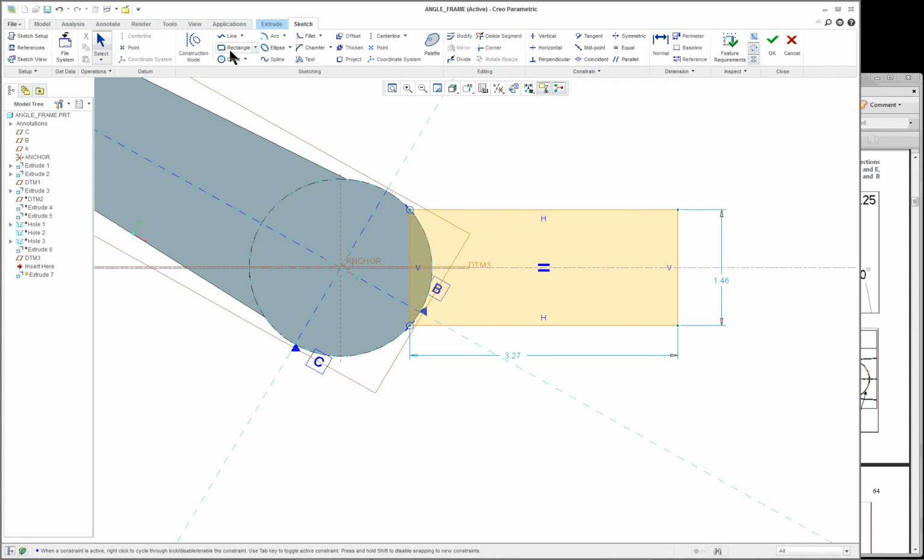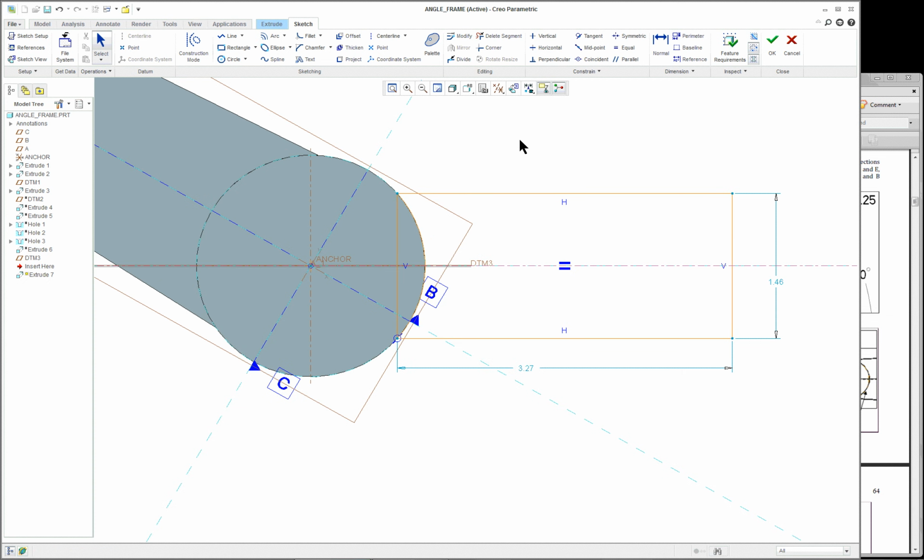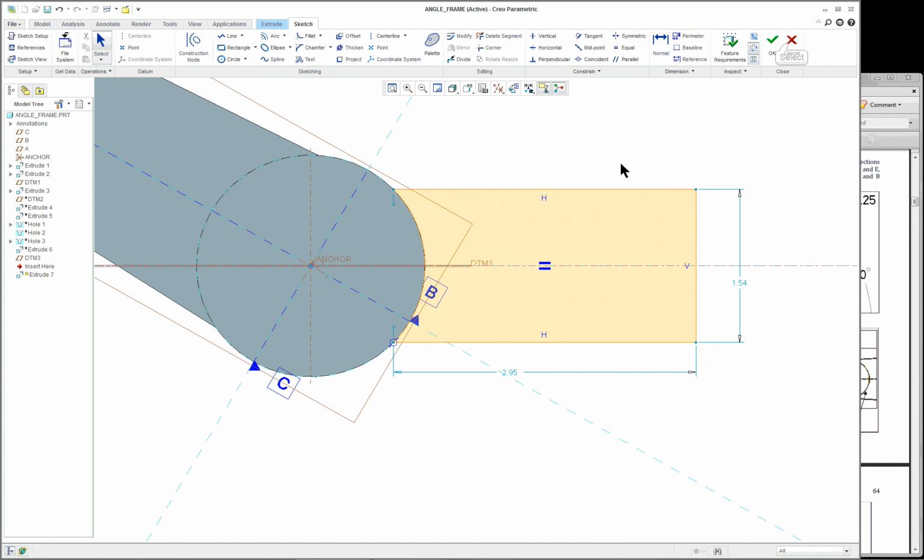So basically you can come up here and select the arc, and let's try the concentric this time. Just click the outer edge and click where you want to start and click where you want to end. Middle mouse button. Now it didn't shade because it's got two lines inside of each other right now. It's not right. The arc is inside of the rectangle. So we've got to remove this line here. Now you can simply click on it, right mouse button, delete, and as soon as you do, you see you're going to get your shaded section. That's how you complete the first part of the arm.